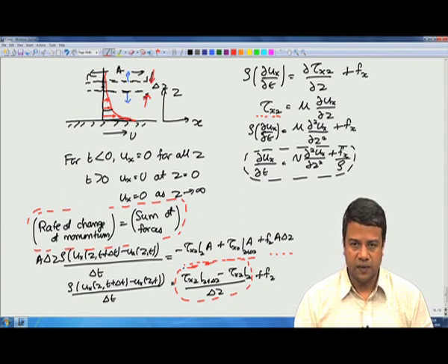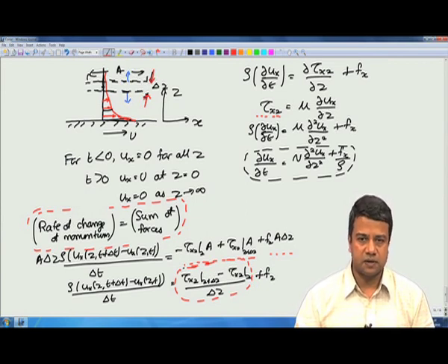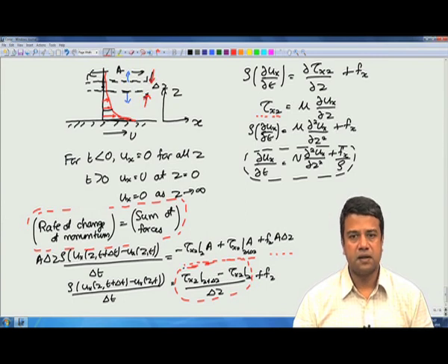The momentum itself has a direction, the direction of the force, and there is also a direction of the surface, the direction of the transport. The force itself is in the x direction, the transport is taking place in the z direction. In other words, the z coordinate is the direction perpendicular to the surface across which the transport is taking place. So, the stress will have two indices. The first one, the direction of the momentum. The second one, the direction in which the transport is taking place, or the direction perpendicular to the surface across which the transport is taking place.